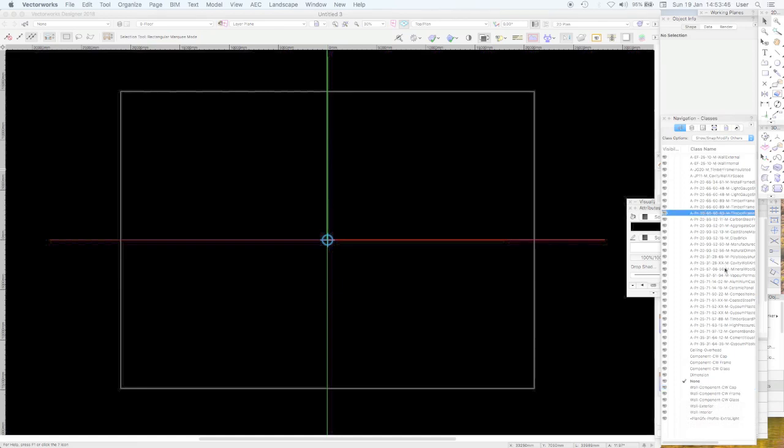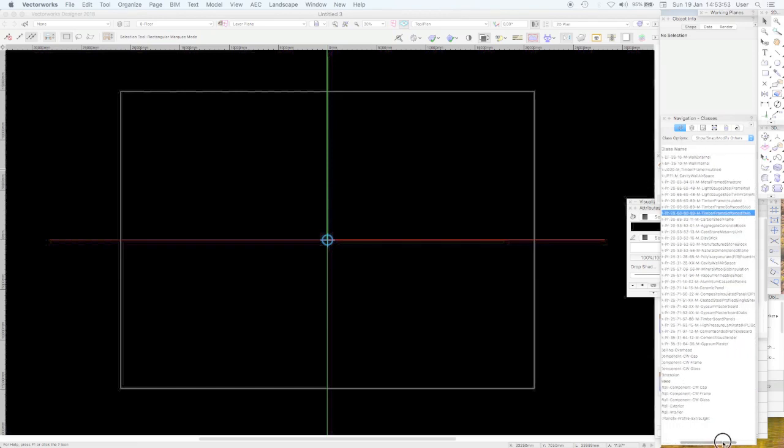So this is the BIM coding. I think this is Uniclass. I mean, for heaven's sake. And look at the length of the file names, because those are too long. When they get so long and you export it to AutoCAD to a consultant, it won't open it. Because it translates the class into a layer name, and the path length from the folder to the document gets too long, it won't do that. That name is too long. We've had this problem many times actually, where the name of the thing is just too long.